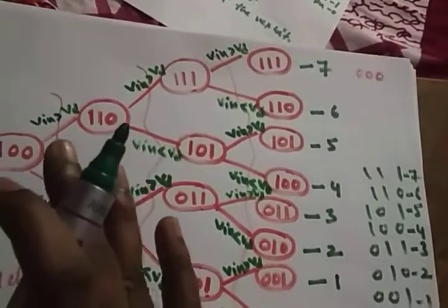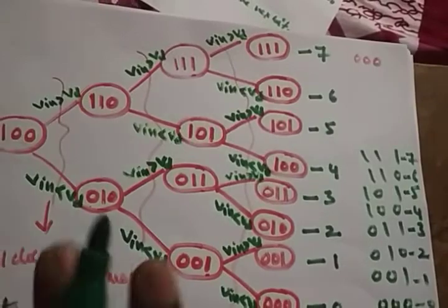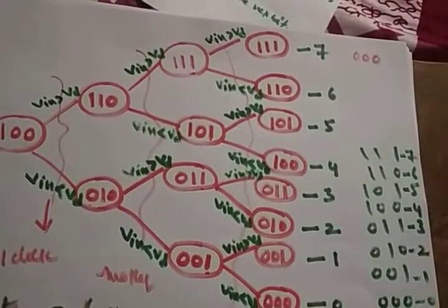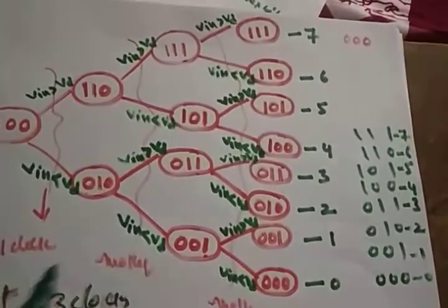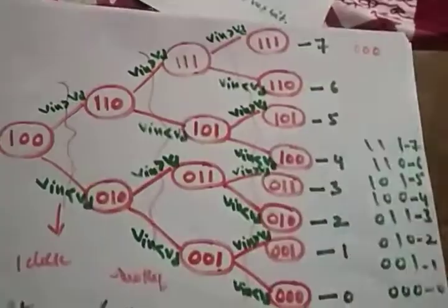Initially, the successive approximation register will set the MSB bit. Next, it will check the condition. If Vin is greater than Vd, it will set the next bit. That's it. It doesn't affect the previous bit. If Vin is less than Vd, you reset the previous bit and set the next bit. That's it. Those 2 things are the entire algorithm approach. Now the concept is clear.